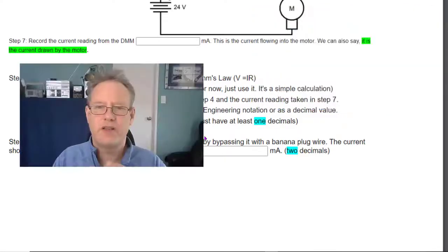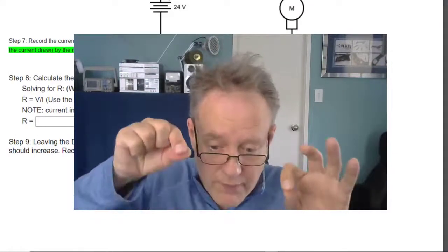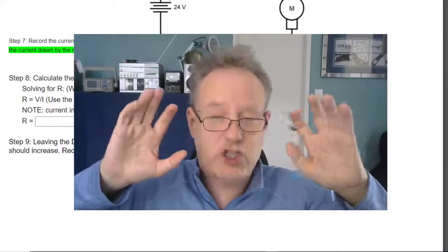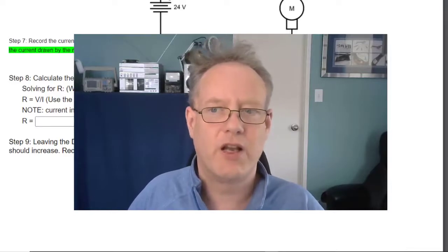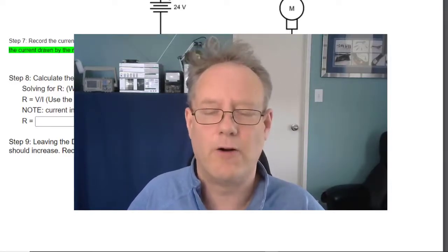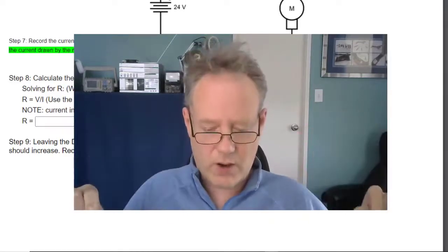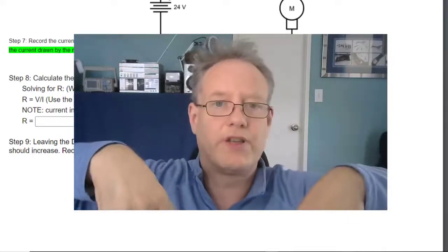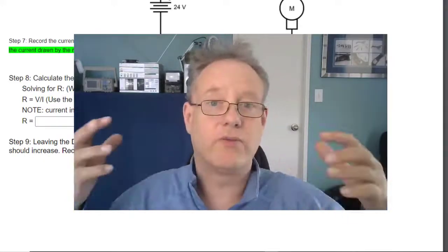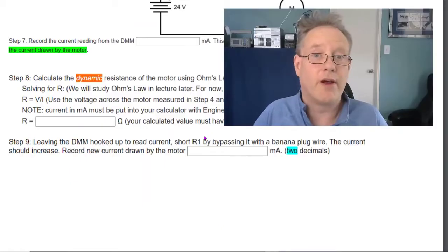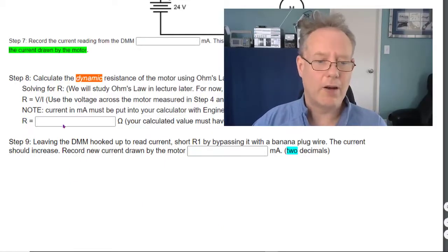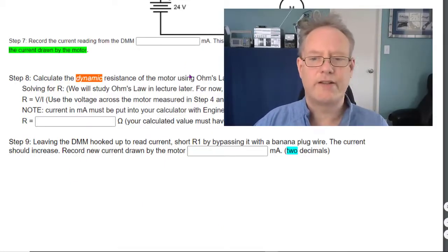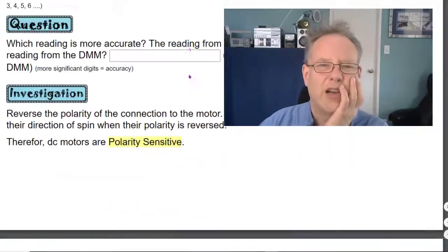Oh, did I say that? Yeah. You have to physically take the wires out of the magnetic plugs in the motor. It shouldn't be hooked up to anything. Actually, the resistors shouldn't be hooked up to anything. Anything you measure of resistance shouldn't be connected to anything else. So disconnect the wires from the motor, stick the probes in there, set the DMM to read resistance, and write the value down. Write it down here. Make sure, calculate. So you've already, somewhere else you measured it.